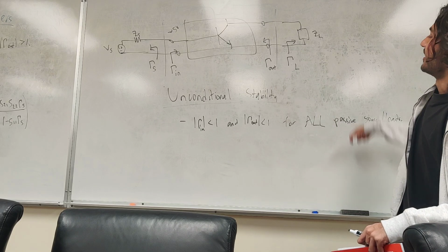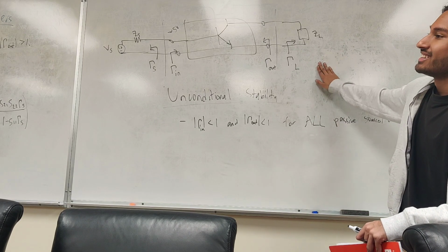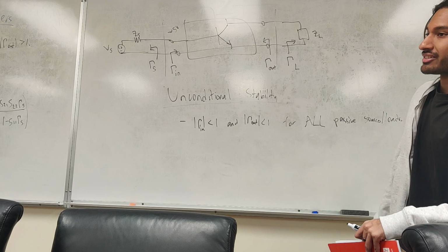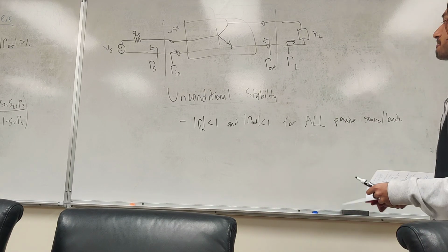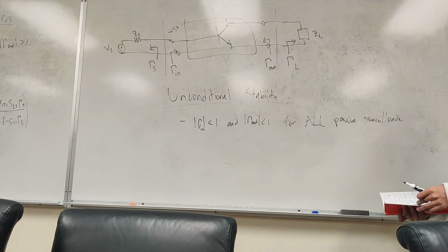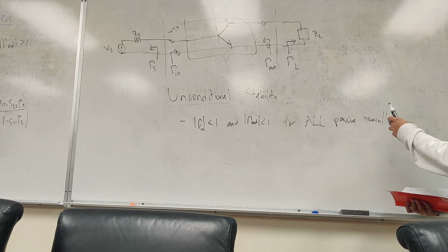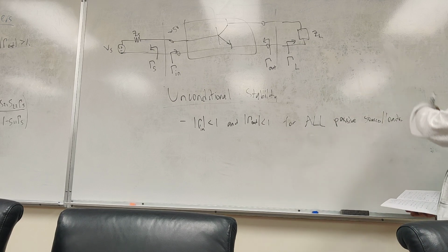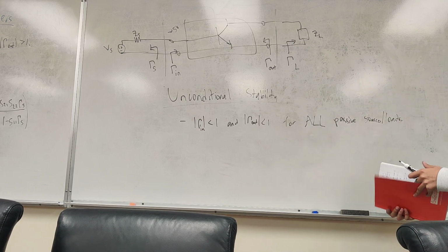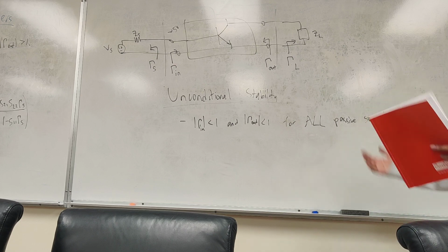Exactly, we are. No. We have a tool that we use, the good old Smith chart, to help us determine how stable we are. Because if you remember on the Smith chart, we normalize to a certain Z naught, right? If we have an impedance of 0 divided by 50, that's 0. If we have infinity, it still goes to infinity. So the Smith chart can encompass all these infinite options we have.